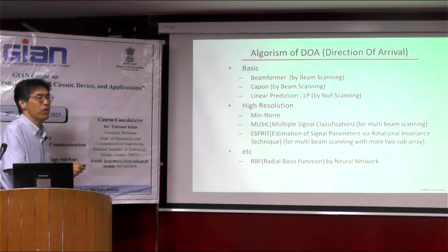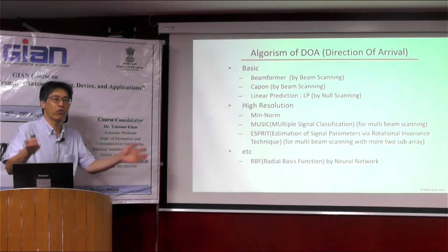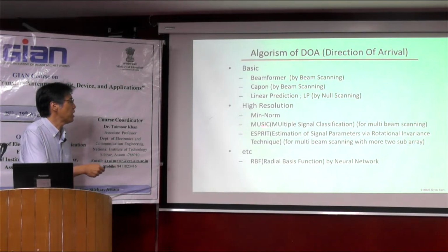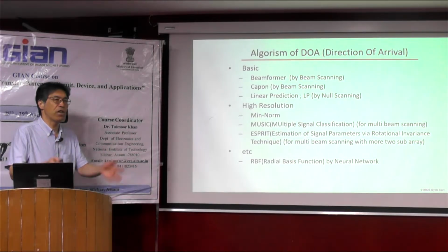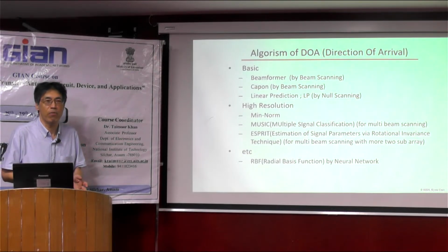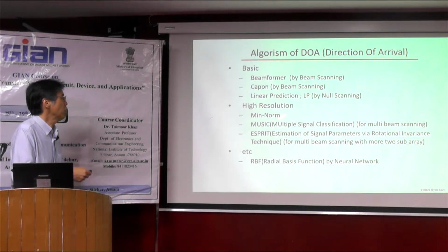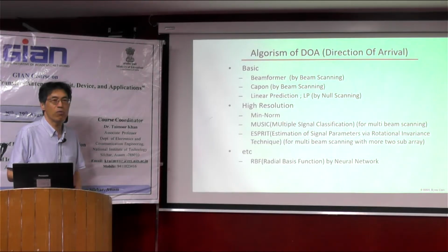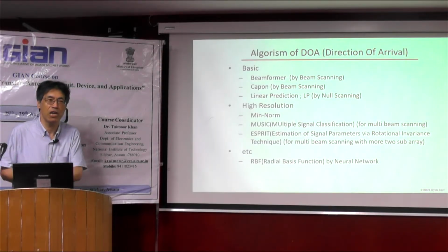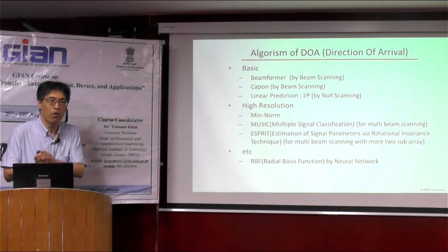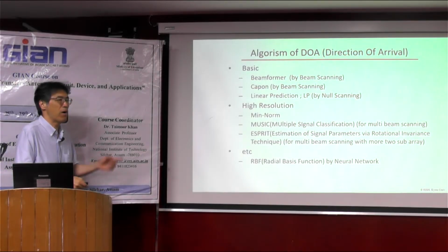The basic method cannot detect two or three multiple pilot signals, but with MUSIC and ESPRIT, we can detect multiple target directions of arrival. So if we have this good technology for the direction of arrival, after detecting the position or direction of the target with the help of the phased array antenna, we can control the beam direction. But it contains one big problem.